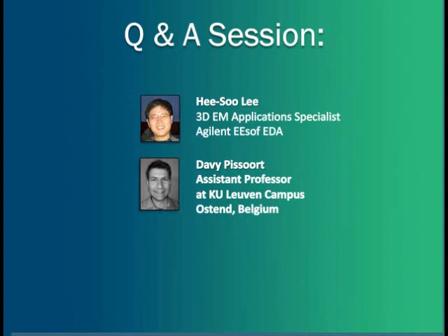typically EMI problems are getting complex and large. That's where we have a little bit more incentive to use the time domain engine, where much bigger size of problems can be handled easily than the FEM solver. So to answer your question, the 3D nature of the problem, the EMI problem, leads to using FEM and FDTD. But in terms of getting a larger and complex size of the problem, FDTD turns out to be more like a better choice for the analysis.